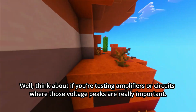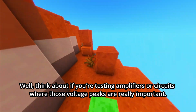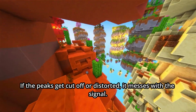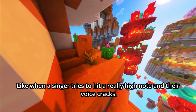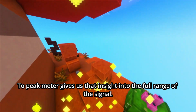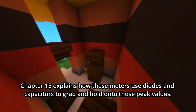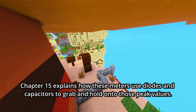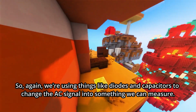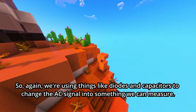Why is that important? Well, think about if you're testing amplifiers or circuits where those voltage peaks are really important. If the peaks get cut off or distorted, it messes with the signal. Right, like when a singer tries to hit a really high note and their voice cracks. Yeah, exactly. And a peak-to-peak meter gives us that insight into the full range of the signal. Chapter 15 explains how these meters use diodes and capacitors to grab and hold on to those peak values. That's how they make sure the measurement is accurate. So, again, we're using things like diodes and capacitors to change the AC signal into something we can measure.